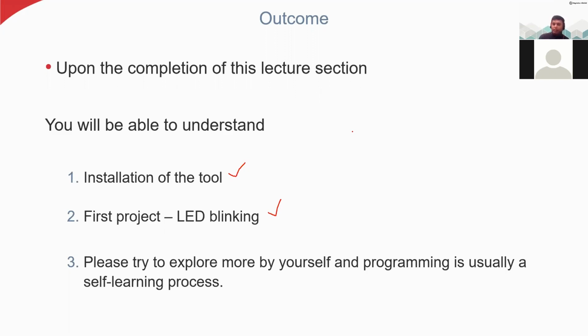You can write the C code inside the compiler, and I will show you where to write the user C code after you generate the standard one. After that you will download the C code into your hardware, that is the microcontroller. Then you will implement the function. So try to spend more time, watch some reference videos and forums, and learn more about this tool and how to use the STM32L476 in practical projects.